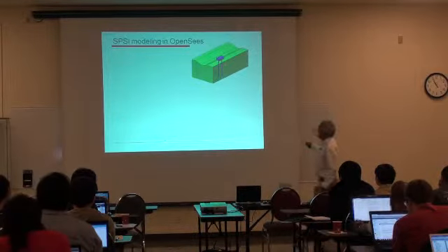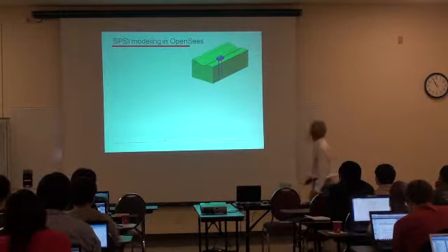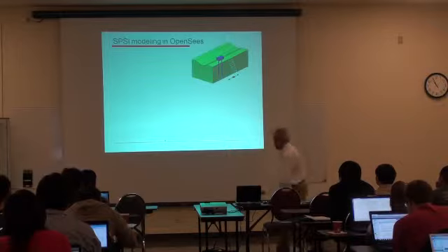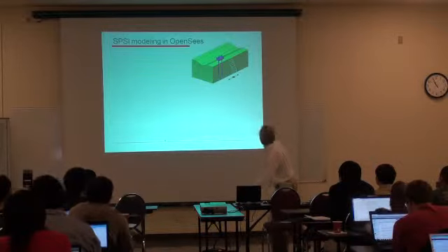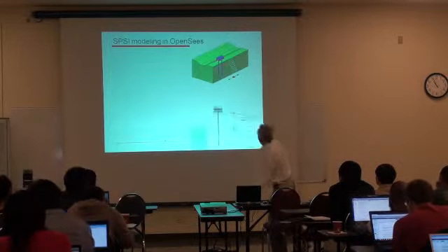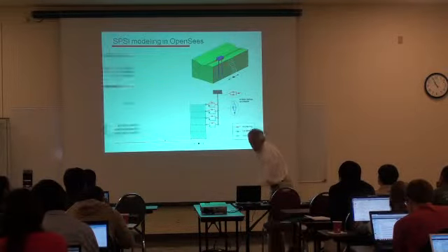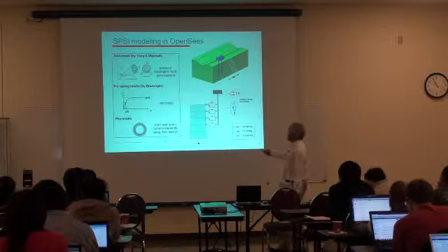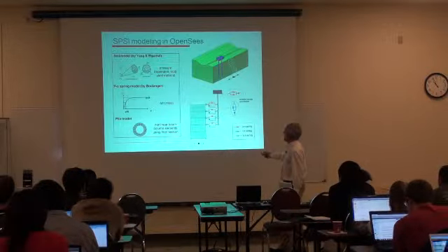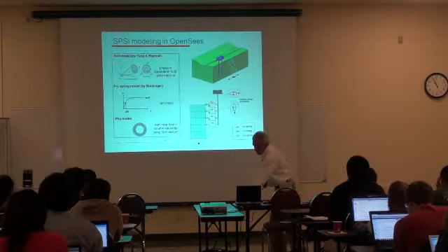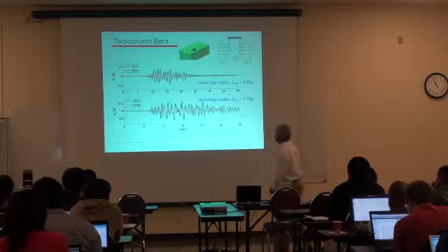And so these are schematics of the centrifuge test for these bands. We apply an excitation here. We have a kinematic excitation that will impose an effect on the piles, as you imagine. And this is the simple model that we use. We use the pressure-dependent multi-yield for the soil, and the PY springs implemented by Boulanger for the PY springs. And this is the cross-section for the pile. We use the fiber section.